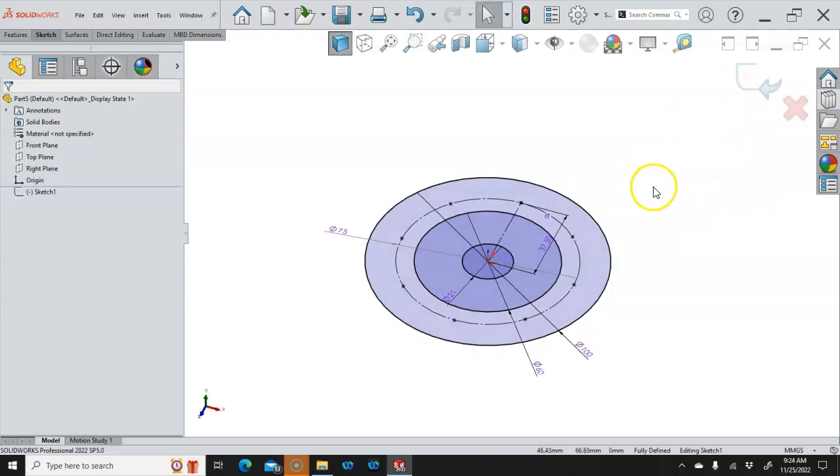I can either convert these entities or I can use this sketch directly. So if I want this to be an envelope, usually for continuity, for somebody else to open this up and kind of see what I'm doing, I would not share the sketch, at least initially.